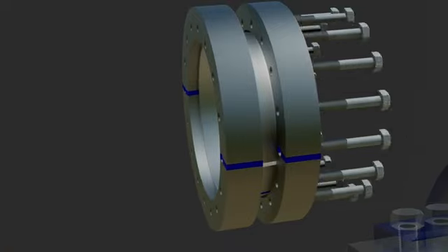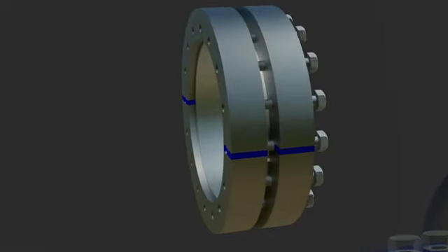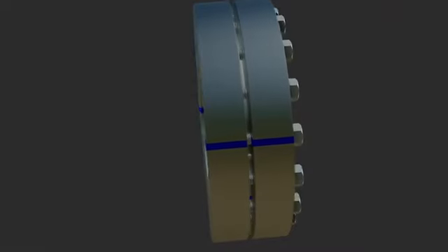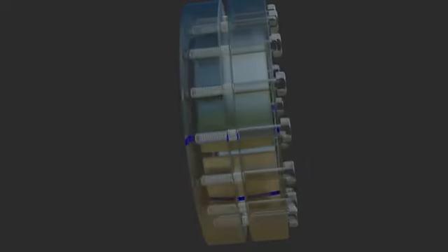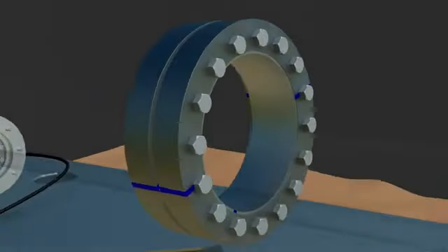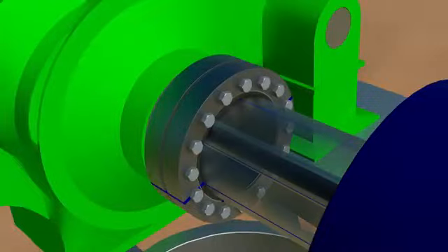And third, high-strength bolts that pull the outer rings together. The screws pull the outer tapered rings towards each other. As the outer rings slide up the tapered slope of the inner ring, the reduced volume forces the inner ring to contract. This contraction exerts immense radial pressure inward on the hollow hub. The pressure reduces the diameter of the hollow hub slightly, clamping it down onto the solid shaft. This creates a friction fit around the entire circumference of the shaft.